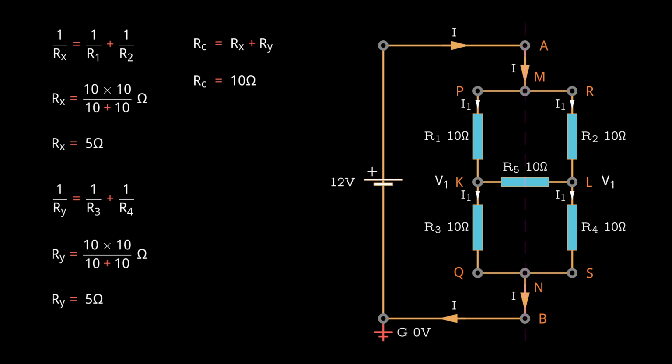As a result, you can either remove the resistor between these equipotential nodes, or add a conductor without changing the overall behavior of the circuit. At this point, if there are resistors in parallel, or in series, replace them with their equivalent resistances. After making these adjustments, continue tracing through the circuit, until you encounter another set of resistors. By following this systematic approach, the circuit is progressively simplified, making it easier to calculate the final equivalent resistance.